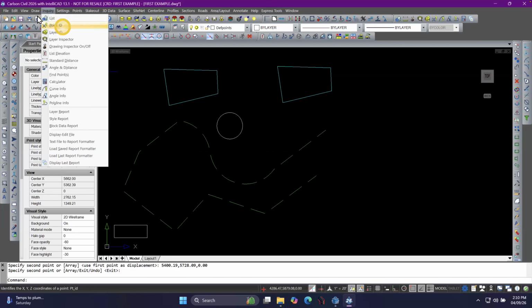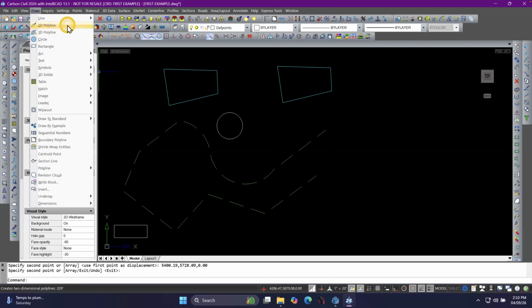A 2D polyline is set at a constant elevation, usually 0, not always. Contour lines are a good example of 2D polylines, but at a specific elevation. 3D polylines go from whatever you show as the XY location, it also gets an elevation. So it can go up and down in space, in and out of the screen.